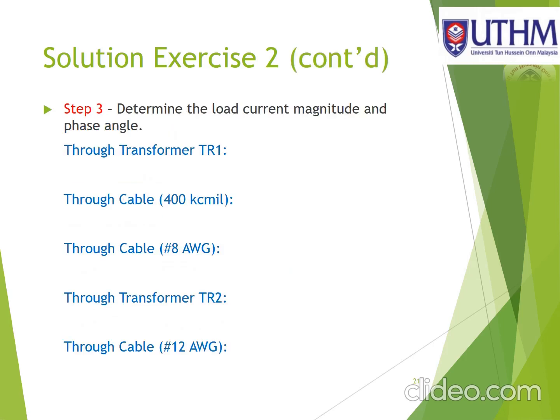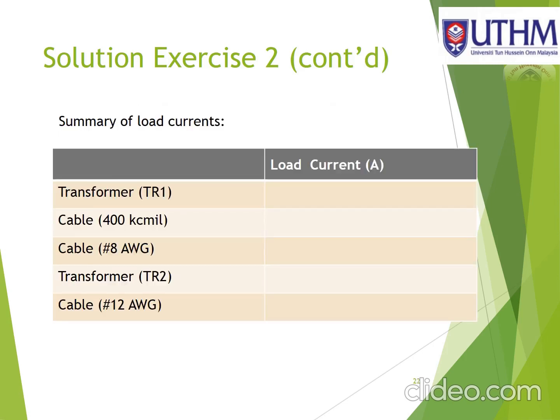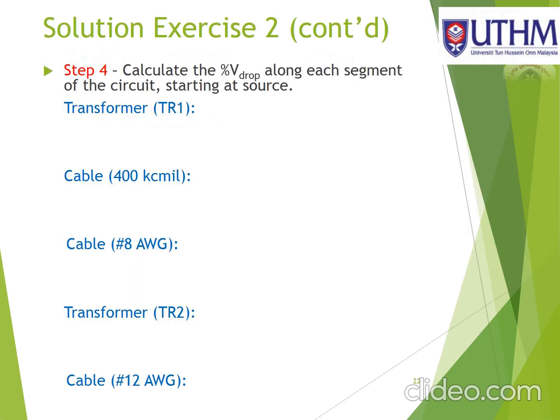Step number 3 is to determine the load current magnitude and phase angle for all segments, and then put all the values of current in the summary of load current table.